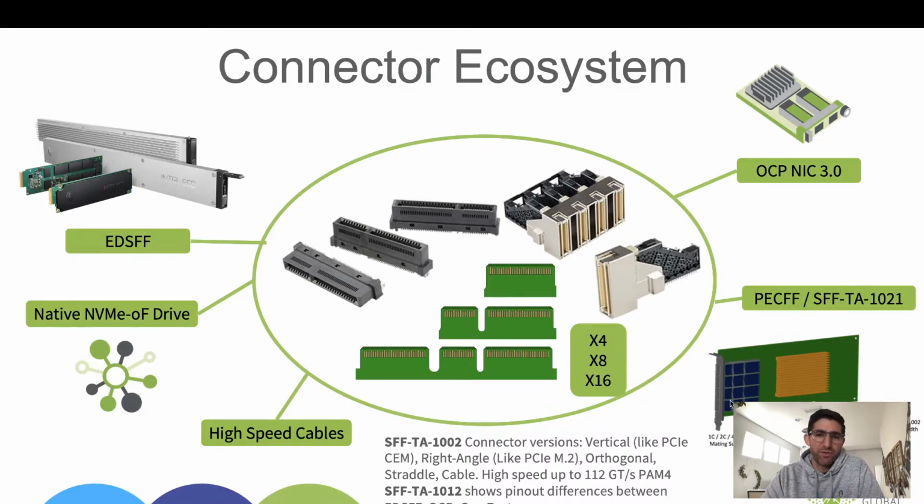And really the most important thing is, we see PCIe Gen 5 going to 32 gigatransfers per second, up from 16 gigatransfers per second in PCIe Gen 4. So you really need better signal integrity on the SSD to basically reduce platform cost and overhead for PCIe Gen 5. So that's where we see EDSFF getting really exciting.